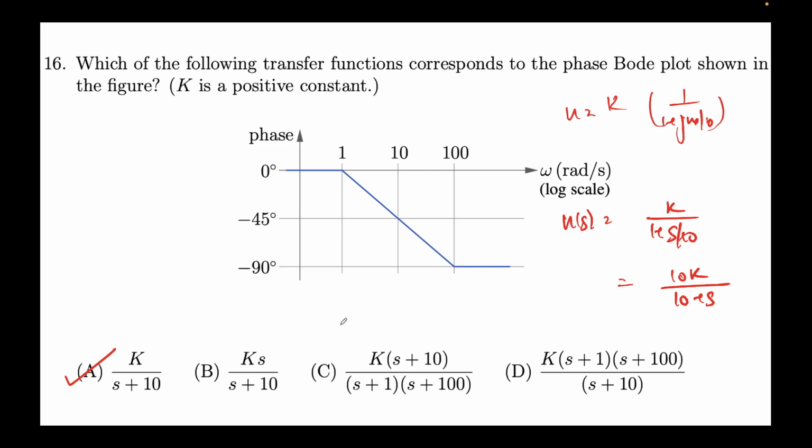So we saw both the flavors, and it's important that you analyze that, because the practical application for op-amps is sometimes to design filters, like we saw one problem where it's a low pass filter. So in that sense you must understand, at least have a basic idea about how the poles and zeros work, single order, double order, and so on. So it gives you an idea to design a good circuit.